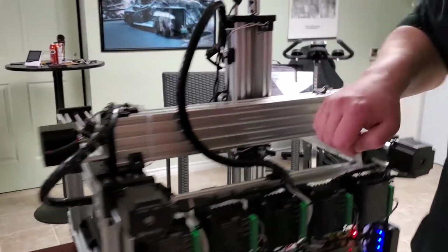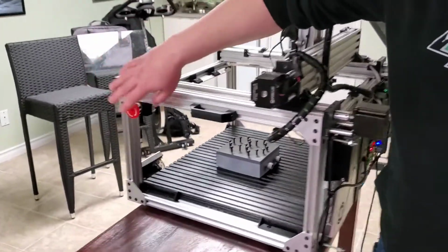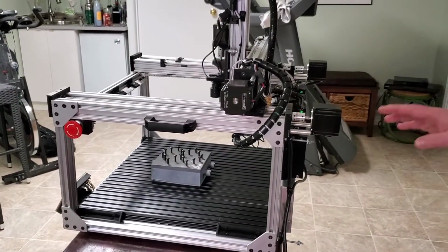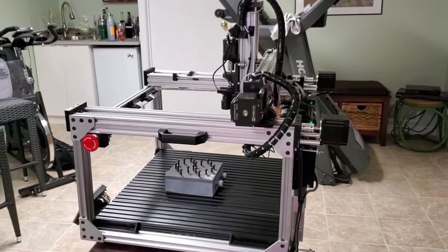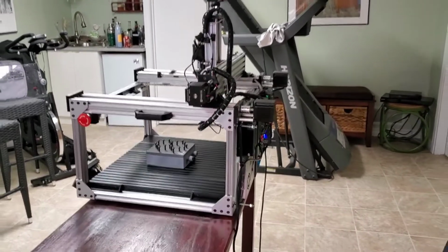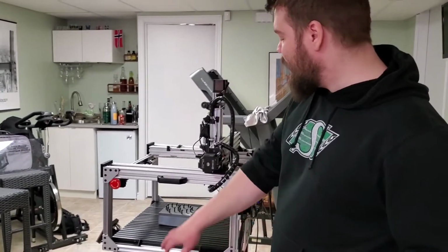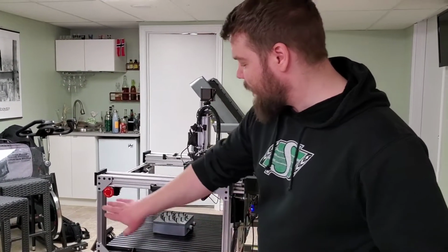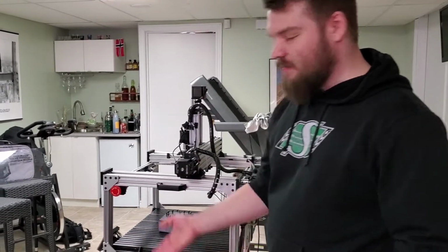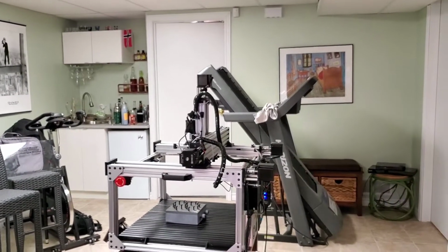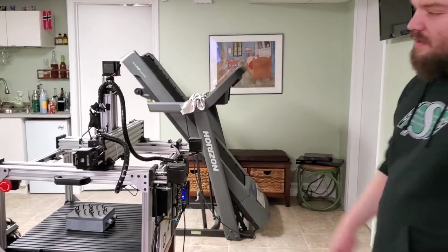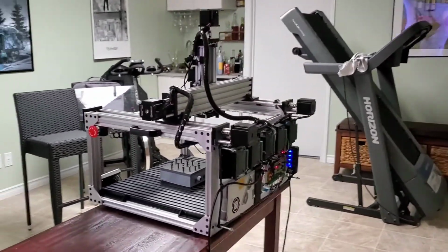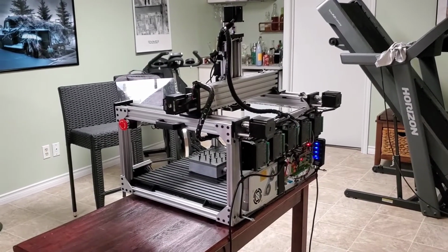On the side here, we also have a kill switch. This is going to kill power, not to the power supply, but to the system itself in the event that something has gone critically wrong. We'll illustrate that by homing the machine, and we should kill it and it should stop right away. So that's effectively done exactly what we said it would. Now that has stopped the machine. If we turn it back on, it's essentially stopped in its place.